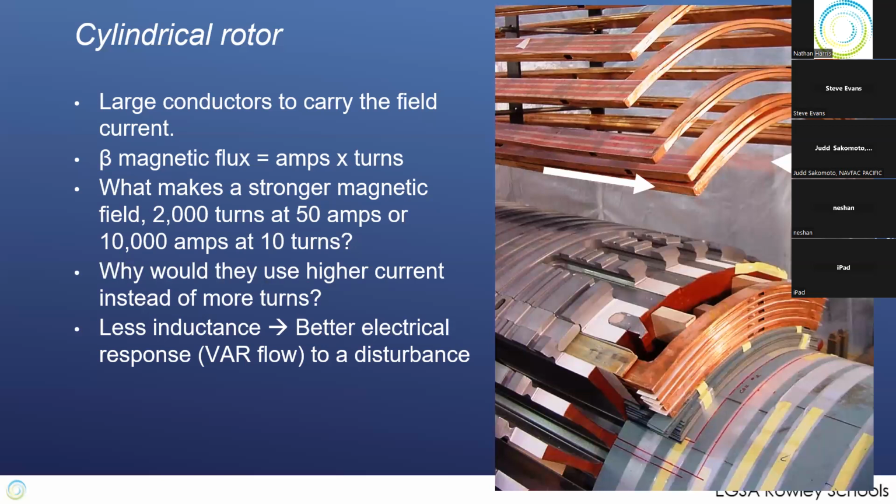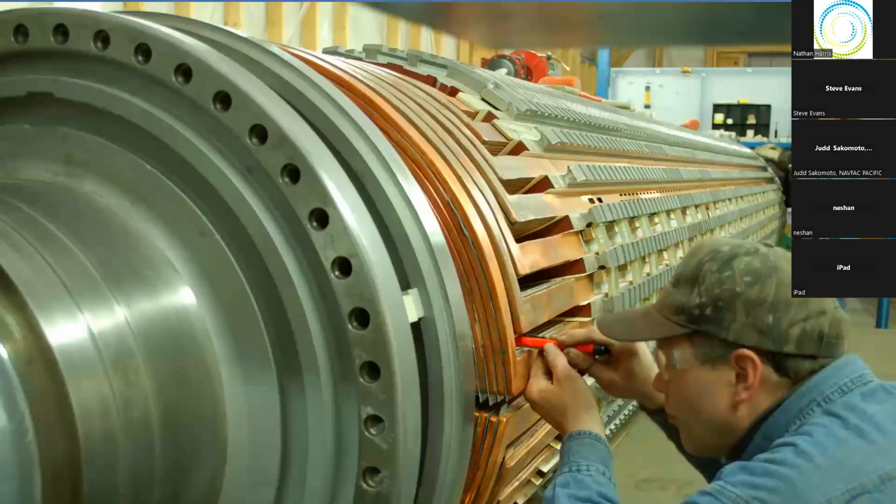Now, we've done things on the regulator side and we can show you that. We look at the response curves. We've added forcing. We've added a differential PID, and the differential regulator used to just be PI. Now they're PID. So we've added things along to compensate for this time constant. But still, the time constant is a factor in how our machine responds to a large VAR flow, and so it gets a better time response.